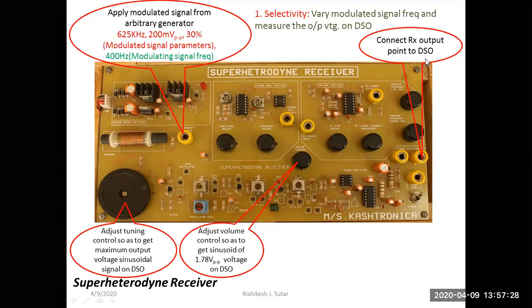Now let us move towards the first characteristic, that is selectivity. Vary the modulated signal frequency and measure the output voltage on the DSO. Here you can take three readings below 625 kilohertz frequency and three readings above 625 kilohertz frequency. We can plot the graph of output voltage on the DSO versus modulated signal frequency.